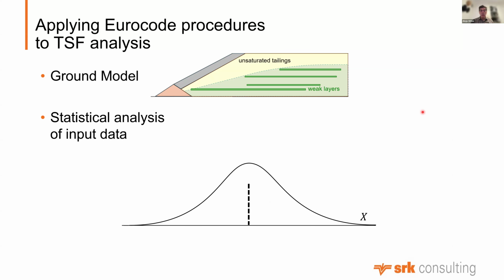So you start with few data points, and now imagine you only have 5 data points. According to the statistical analysis that is mandatory, compulsory, you have to use, you end up with a design characteristic value that is conservative, because the lack of enough data means that you are not certain about your mean and the statistics of your data.